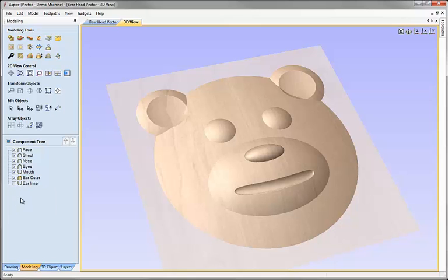So if we switch off that last shape there, we can see all these are just adding together. The first four are just adding, sitting on top of each other. Then the mouth is being taken away, we set that to subtract. The outer ears are being blended into the head, but then that inner ear is subtracting from everything that's happened previously. So it's subtracting from the outer ear and from part of the head that it overlaps here. What we'd actually like it to do is just subtract from the outer part of the ear, and then for those two to blend together with everything else.